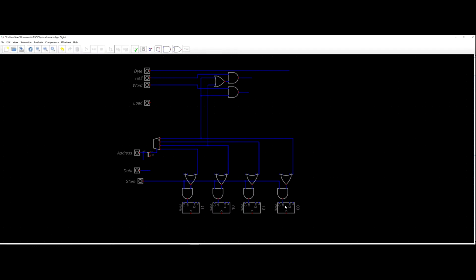So what I did is, since I'm limited to 2 to the 24 bytes in here, I'm saying I have 2 to the 26 bytes I can actually use by splitting them up, because I have 4 different spots I can write a byte to. So I multiplied my amount of memory by 4 by doing this. But anyway, back to the problem at hand.